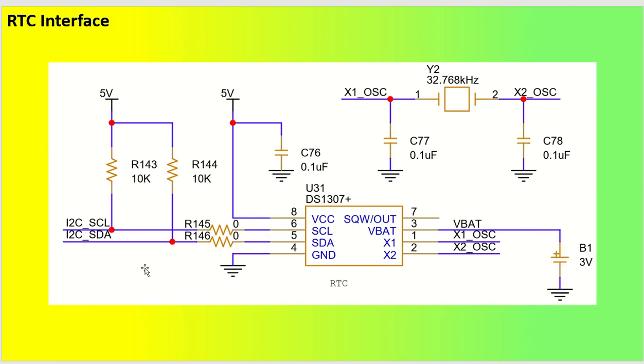Now, one very important application which is generally used externally in low-end, low pin count microcontrollers which do not allow RTC application built in. So in that case, RTC functionality can be utilized externally. This is an RTC IC, the DS1307+, from Maxim Integrated.